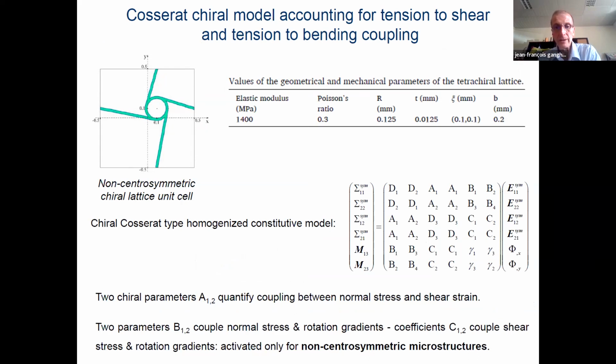So here we write in 2D the constitutive law. In this constitutive law, we decompose the stress into a symmetrical part and a skew symmetrical part, but here I'm just writing the symmetrical part of the stress with 4 components, and the second part is actually the bending part relating the in-plane bending moments to the microcurvatures. So I expect to have a fully populated matrix.